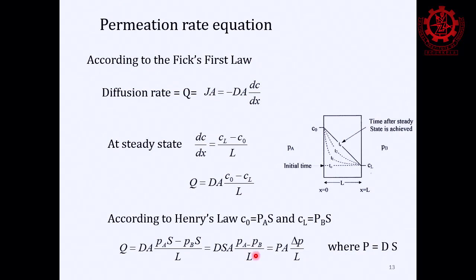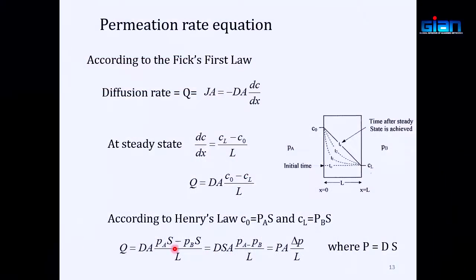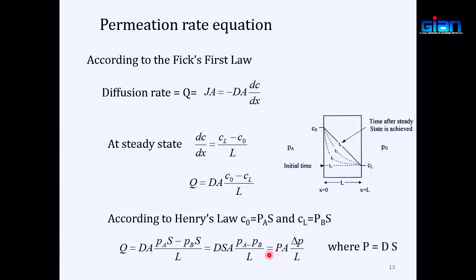Yeah, the only thing you can change here is the permeability. So go for the film which has higher oxygen barrier properties. This is how these kinds of mathematical descriptions can help you either design a film or select a film. In terms of selection, whatever films are there, you just see what permeability with respect to oxygen it has. You plug it here and it can give you time.